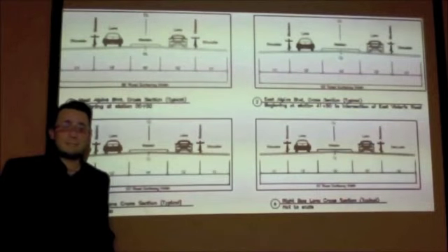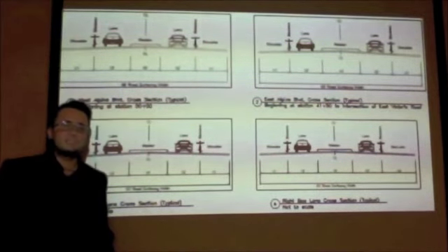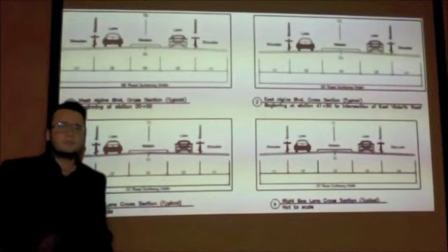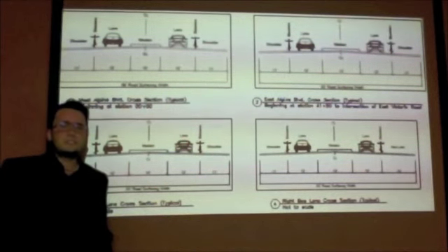In order to provide enough space for public transportation buses, the locations where bus stops are present will be modified. Instead of the normal 11 feet shoulder that is throughout the boulevard, at these locations a 14 feet shoulder will be used.